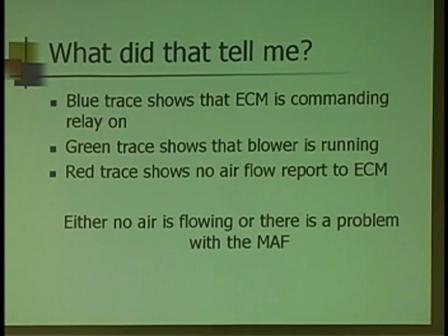So the blue trace is telling me that the ECM is indeed powering the relay. So all the conditions that it wants to see have been met, and it's doing its job. So do I need to worry about any of that? No. The pump motor is showing current flow, so the relay works, the circuit's intact, the blower motor is operational. Remember, I'm looking at a system that only runs for about 30 seconds. I got this information in about 15.